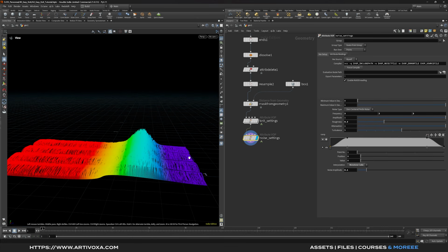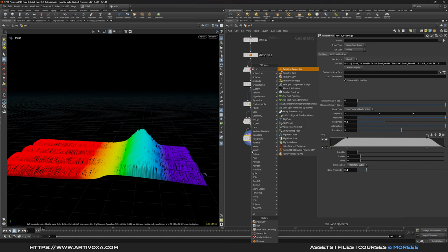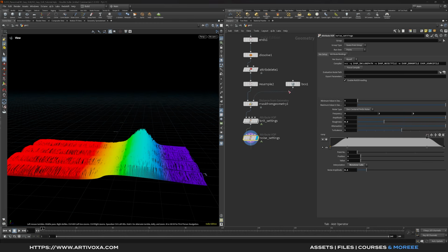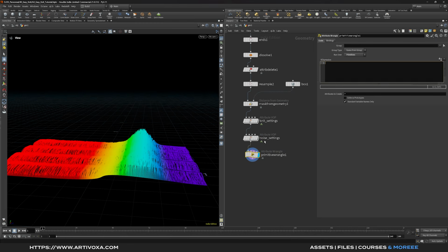So now let's remove some lines to create this reveal effect. So let's add a primitive wrangle. And here with this primitive wrangle, you can type something like if @mask is below, and here you can create a channel float. In that case, you can control the value very easily. So let's type chf, and here you can type mask val, and here you can define our functions. So let's use the removeprim, and here you can type 0 for the first input.